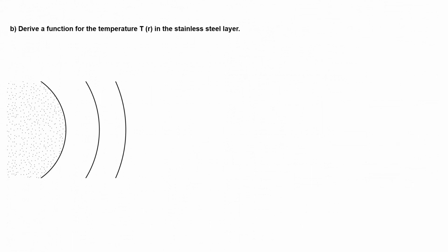The next question is to derive the temperature function inside the stainless steel layer. And again, we'll do this by setting up an energy balance. For this task, we need to solve the heat conduction equation, which is a differential equation that results from the energy balance of an infinitesimal element. So we'll define a coordinate system and take an infinitesimal element inside the stainless steel layer.